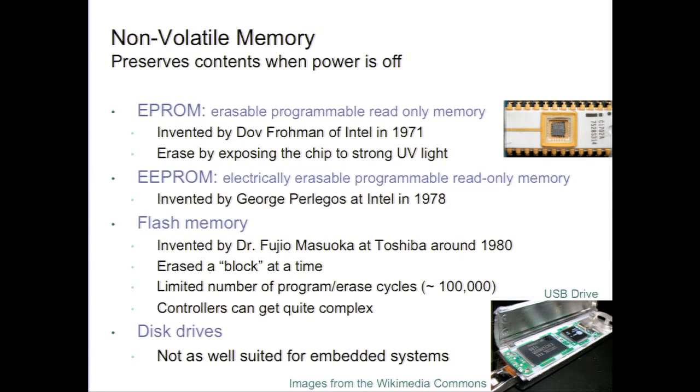Okay? Now, hopefully, I guess the controllers for these things are actually trying to optimize so that your whole memory will fail all at once, right? So they're actually remapping the memory continually to try to keep it balanced so that the rewrites are occurring across the whole memory, which creates a very interesting control problem. In fact, I've been to conferences. There's one conference that I go to every year where literally 1/3 of the conference every year is devoted to research papers on managing flash memories. Okay, and there's all kinds of optimizations you can do if you're interested in operations research, right? And the optimization problems that they do, there's a good application for them, flash memories.